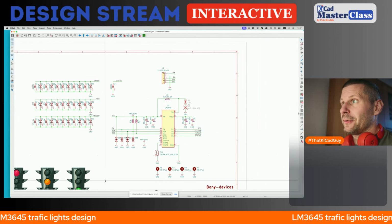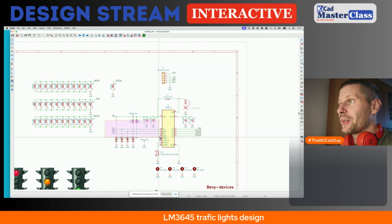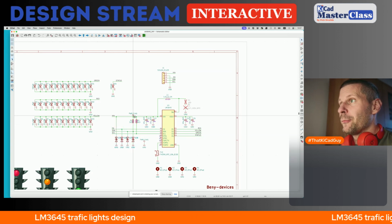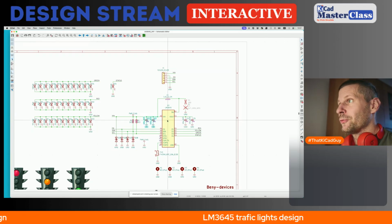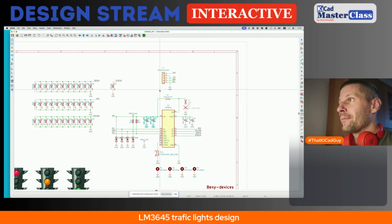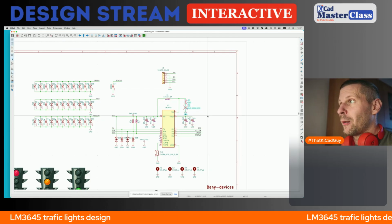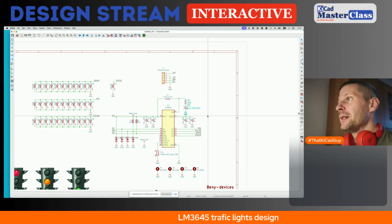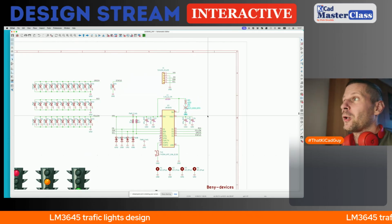This is I2C drivers, so ESD diodes, pull-up resistors for I2C, some decoupling capacitors for input voltage of the driver, and an inductor for the boost. There are unpopulated snubber components as described and recommended in the datasheet. I think the snubber components are requested.